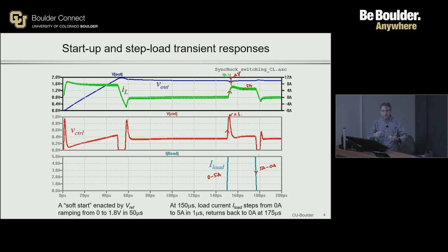the opposite type of action happening in the converter with, again, there's going to be some delta V right here. The homework 1 assignment asks you basically just to find this first one, right? So when you have a 0 to 5 amp transient, how much does the voltage drop in response to that transient? Okay, so I think this is probably all I wanted to say about this very quick introduction to using SPICE to do transient analysis of switching converters.